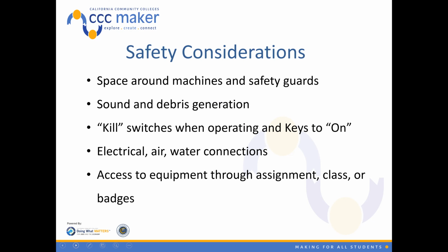Some of the less obvious are kill switches or keys to turn on machinery. These seem to be quite helpful in terms of not only safety, but also makerspace management, where if you have a key that needs to be checked out to turn on the machine so that no one just walks into the makerspace and turns things on their own, this would be a good way to regulate who has access to it by checking out a key and then checking the key back in. And of course, kill switches are for when the machine is operating: does every machine turn off at a given moment if something were to go wrong, lifting up a lid, a big red button, things like that, and most do.